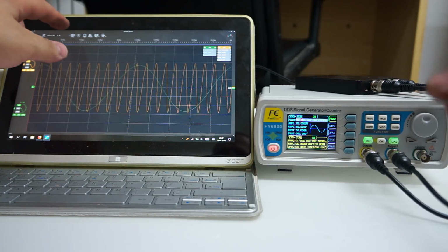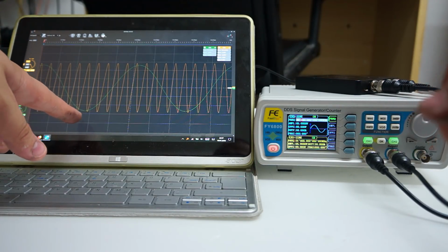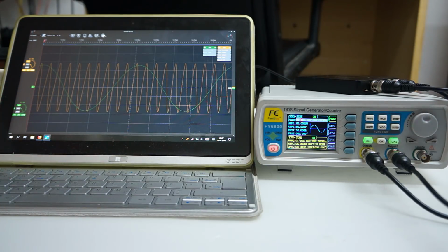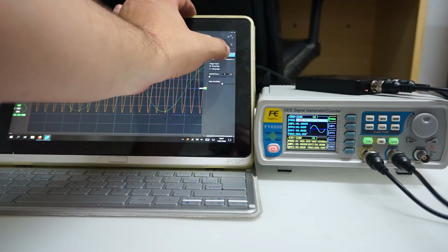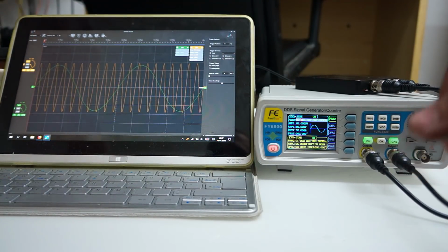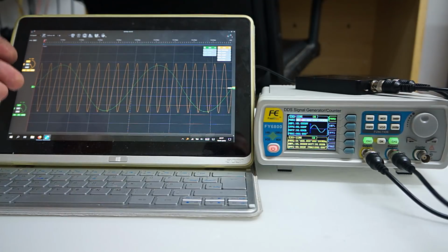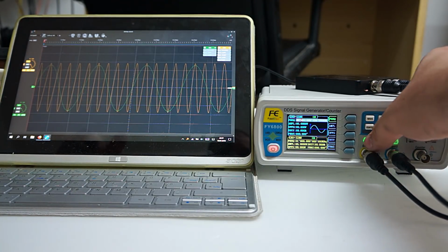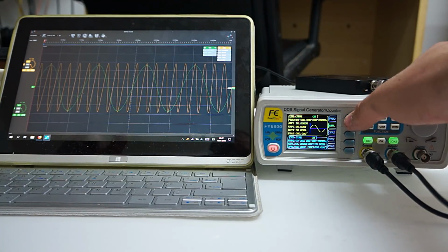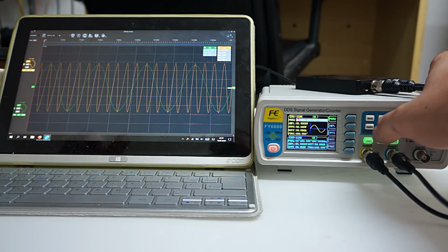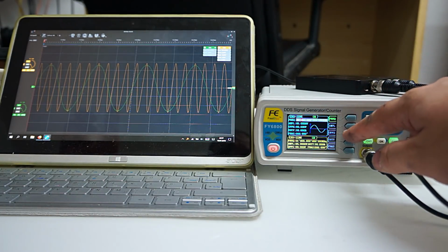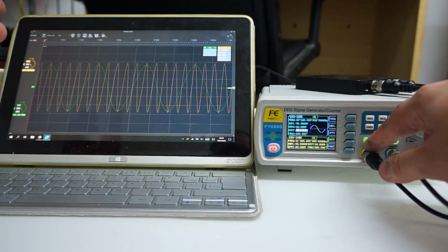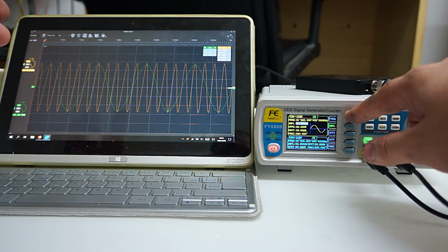There we go. I just stop the scope and we can see the green line, which is barely visible on the camera. We can also set the trigger on the green line. Let's do that. Just channel 1. Start. And now the waveform is rock solid. Or we can change channel 2's frequency or channel 1's frequency if you select channel 1 and then frequency. It also remembers the cursor. If you go to amplitude on channel 1, select channel 2, I'm back at frequency. Let's change this to duty cycle and go back to channel 1, and we're back at amplitude.